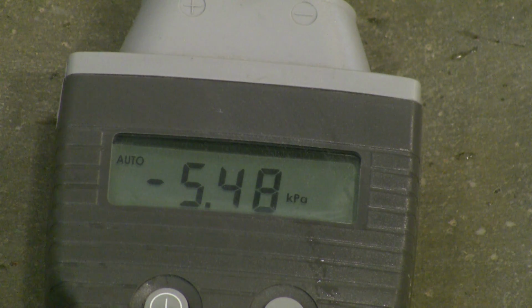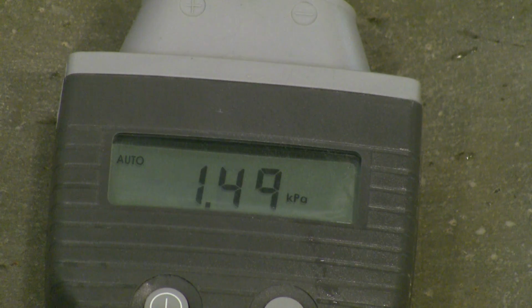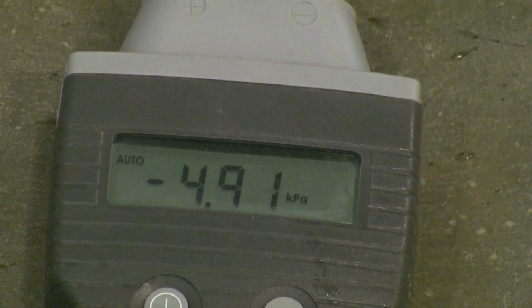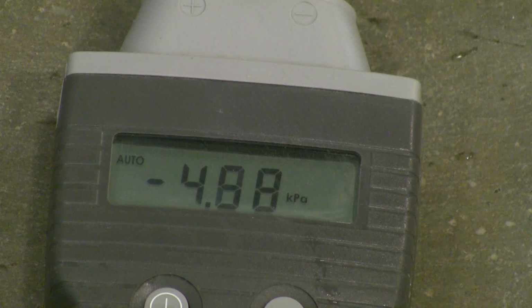Previously the instrument wouldn't zero, and that's because one of the sides of the device wasn't measuring pressure at all. So if I close the valve and the flow stops, it is now holding a zero or pretty close to it. And I open back up and we're measuring a pressure difference. Now I did turn off the bench for just a moment, but I didn't change any of the valve settings.